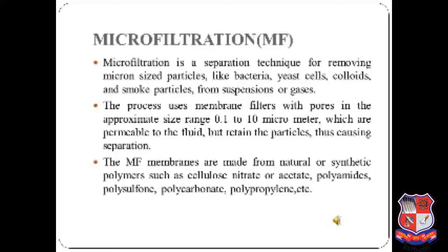The process uses membrane filters whose pore size range is approximately 0.1 to 10 micrometer, which are permeable to the fluid but retain the particles, thus causing separation. The microfiltration membranes are made from natural or synthetic polymers such as cellulose nitrate or acetate, polyamides, polysulfones, polycarbonate, polypropylene.